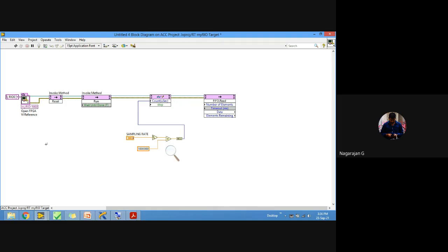The host computer can be a Windows based computer or it can be a myRIO RT target. Both the Windows operating system and the OS which supports the FPGA interface functions are supported. In addition, we can use the FPGA target interface functions on the RT target to communicate with the FPGA. So when we use the FPGA VIs and functions to communicate with FPGA VIs from the host VI, the VI that runs on the FPGA target is called the FPGA VI here.